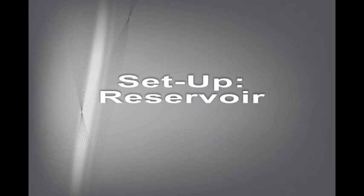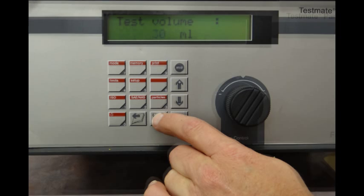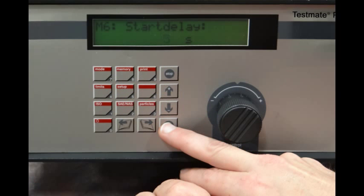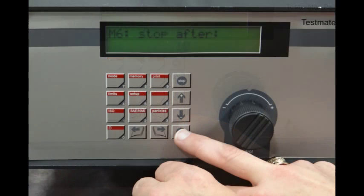Setting up the TPM for a reservoir sample is very similar to the bottle sample. You'll still want the measured volume to be 30 milliliters. Once again, you'll want to select mode 6, Auto Stop, and again, you'll set the start delay to 5 seconds. Setting the limits is where things change. We'll want to take many different samples instead of just 1. Set the stop after to 10.